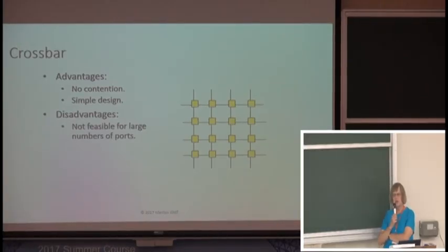It costs you n squared. You have n inputs and n outputs. The area is n squared. Good news is at least those cascades are small. Delay also is significant, but for the size of crossbar we're talking about on a neural network, probably not that bad. We can probably afford to do that.